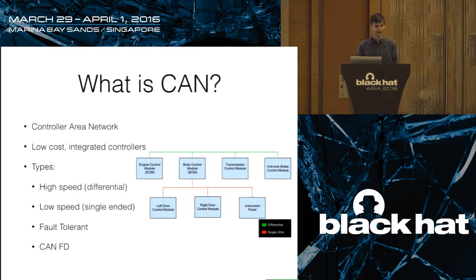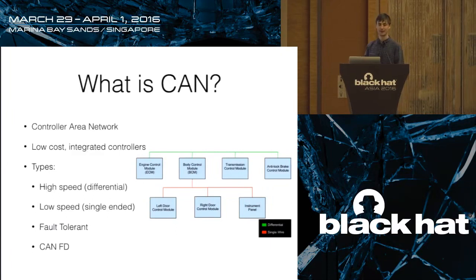But a typical CAN bus that you look at is going to have a collection of controllers that are all sitting on a bus. Now, it's important to note here there is no switch like an Ethernet network. They are all just connected up to that bus. So everyone has the ability to control the bus at any time, and using an arbitration technique, they actually manage to decide who should talk when.